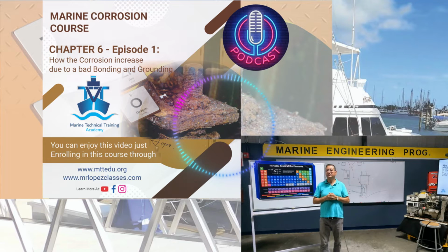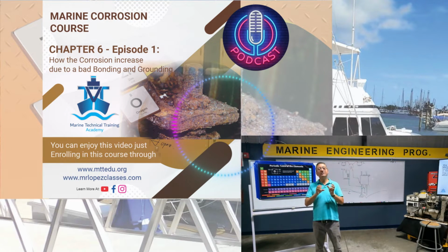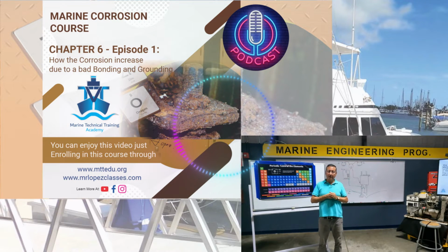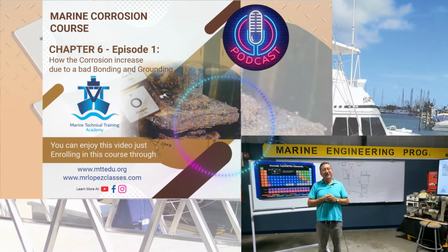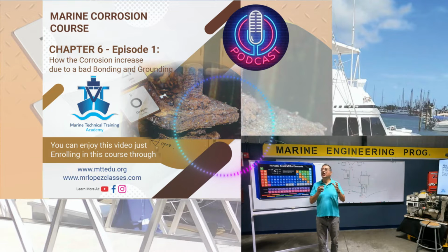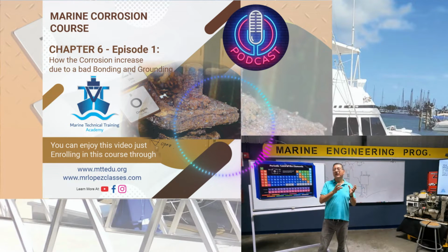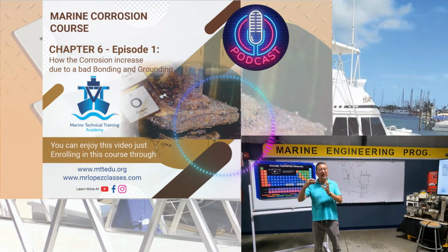Or the starter motor in a big diesel engine. If the negative is loose on the battery, during the cranking, you can explode the battery. The negative is critical. Or the typical example, the customer complains: when I start the generator directly on the control box, the generator starts properly. When I try to start the engine from the flybridge or from the pilot helm, the engine doesn't start.